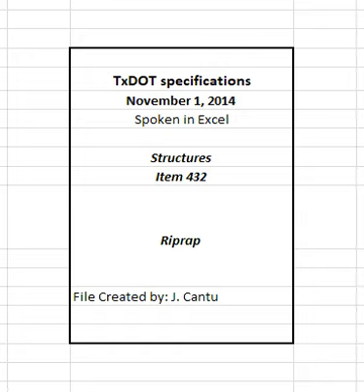3.4 Cement stabilized riprap. Follow the requirements of the plans and the provisions for concrete riprap except when reinforcement is not required. The engineer will approve the design and mixing of the cement stabilized riprap. 3.5 Special riprap. Construct special riprap according to the plans.